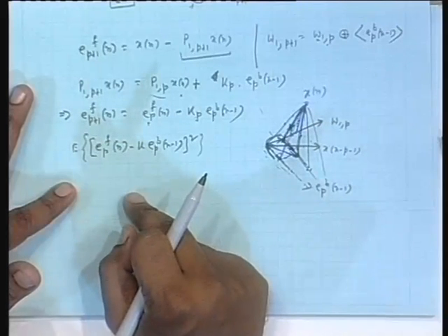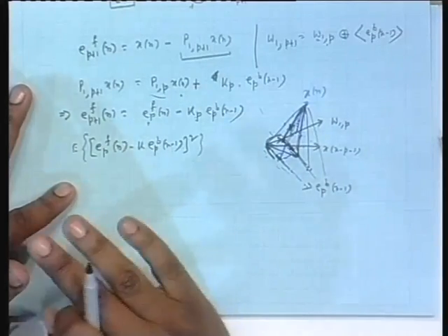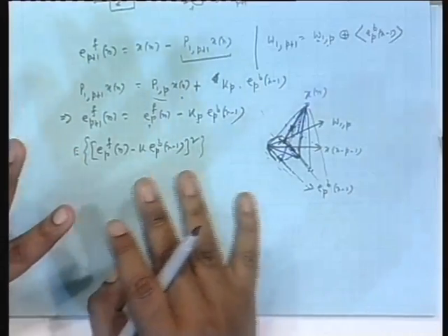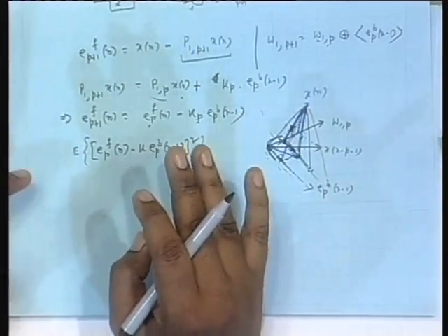Okay. So suppose I carry out a steepest descent now, that I don't know what the optimal k is, like in the case of the optimal adaptive filter. How did we go to the adaptive filter? First we started with the optimal filter, we had the expression R inverse p, and then I said suppose I don't know how to compute R inverse, or R may change from time to time. Suppose I do an iterative procedure, I said the steepest descent search.